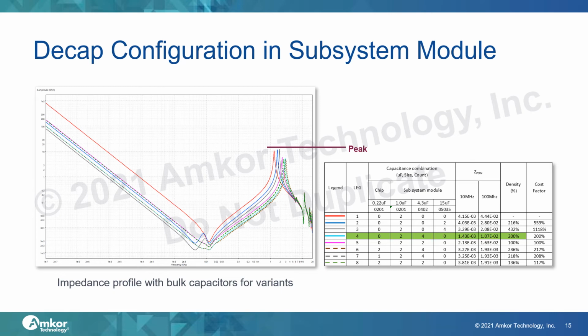The main advantage of a 3-terminal capacitor over the traditional 2-terminal capacitor is only reduced ESR. It leads to lower PDN impedance and improved PI. In this result, this table shows a cost saving by reducing capacitor count.